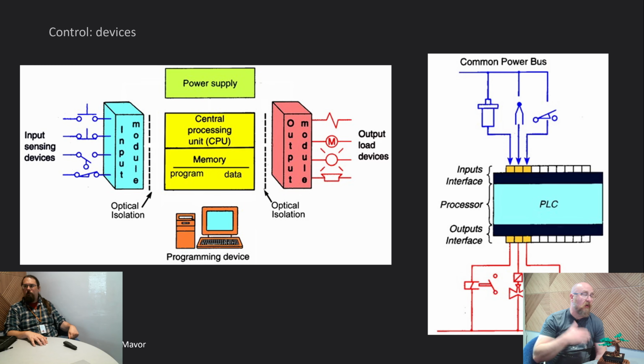But there's a threshold that's less than that, and that's going to vary by manufacturer. That's a specification that you will need to understand, depending on the PLC and the machine that you're interacting with. That will come into your troubleshooting of its I/O and those types of things.